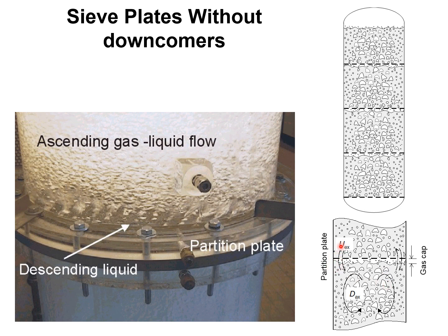There is also some degree of liquid exchange between the two compartments, and within a single compartment you may assume that the gas liquid flow is well mixed. And by introducing several plates, we compartmentalize the column to achieve, say in this case, 4 well mixed stages.